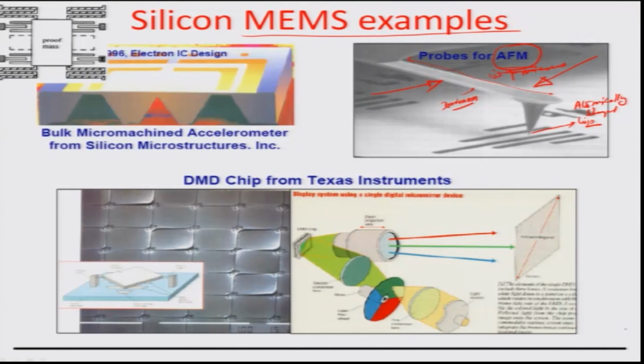Such an object is a very important tool for scanning surfaces, where there are hills and valleys and some surface roughness. You can merely scan this over the surface, and from the deflections that it suffers, you may be able to reconstruct the surface over which it is being scanned. There are two different modes in which the AFM can be operated, that is the touch mode or the tapping mode. This is a very important example of how a microsystem plays a very critical role, because the mass of this particular tip is so small that its own inertial effects are quite negligible.